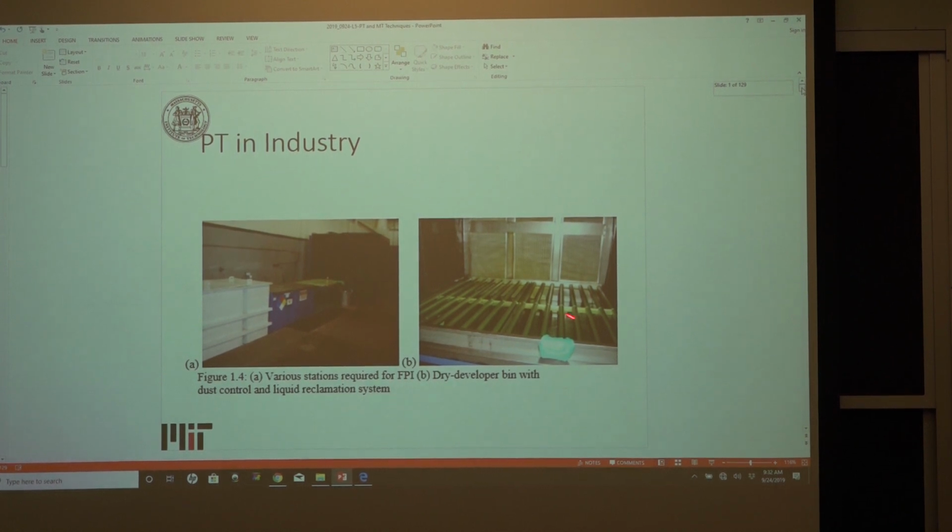So what's happening here is these are aerospace components, and they put the fluorescent on it and they just let it drip off. So this is a bath underneath here. They reuse the material that drips in that bath, but they can only reuse it a certain number of times. So in industry, they have a quality assurance, quality control program, and there are procedures and protocols that dictate how many times they can reuse the penetrants and things like that.